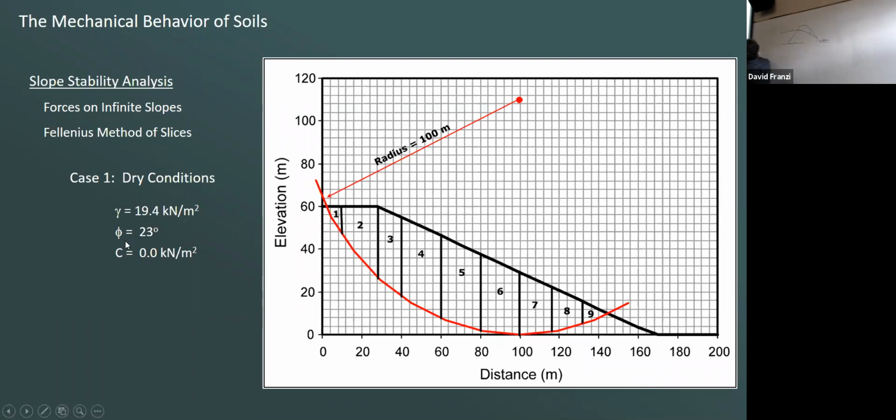That's the elevation of the red line, the upslope part and the downslope part. So you're at 60, and then you're at about 48. Does that matter for the calculation? It does, because that's going to give you your height. You want the average of the difference. So that would be the 12, which divided by 2 gives you 1/2 the height.